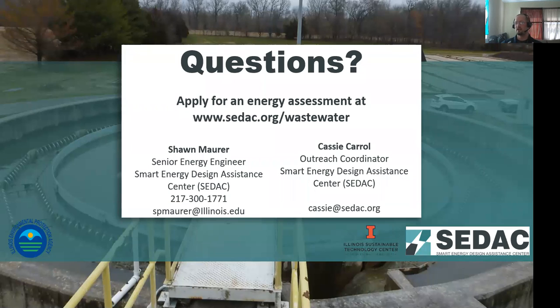Those systems are very, very energy efficient. There's an EPA report that, depending on whether they're motor driven or air driven, they use 30 to 50% less electric consumption than standard activated sludge systems. The one thing we do note is that historically, the rotor arms and axles and bearings for those systems have had maintenance issues in the past, and so in the 80s or so, rotating biological contactors started falling out of favor in favor of activated sludge systems.